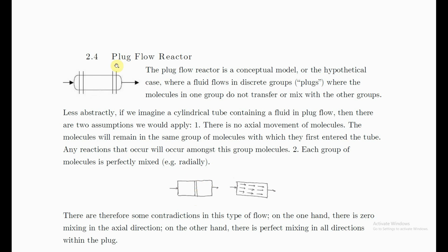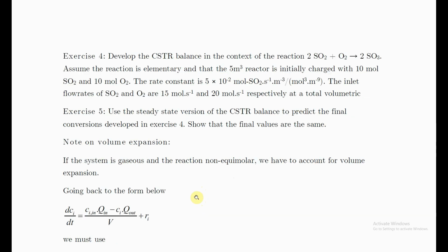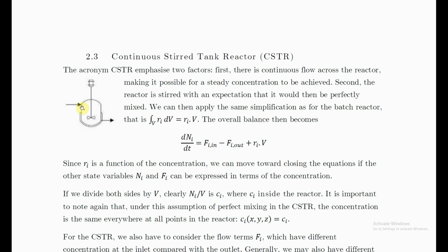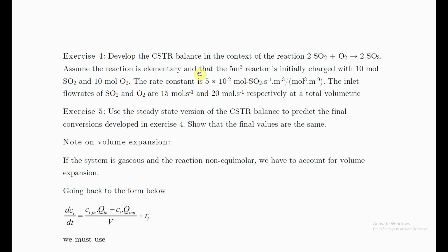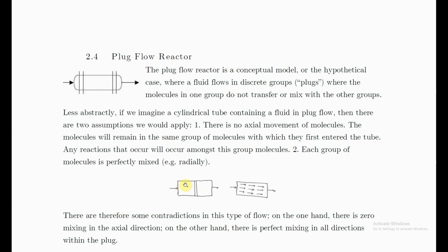So that's the name, a plug flow reactor. It flows in plugs, and each plug is its own entity, and it has all its behaviors internal to that plug. And if you like, that's the perfectly not mixed case. So we had the perfectly mixed case here. Every molecule was mixed identically across that whole reaction space, so you had one concentration everywhere. In this case, it's perfectly not mixed. Every molecule is held in its own individual space. It's chugging along with its peer molecules, if you want, and they're all coming in at the same time. They'll all spend the same time here, and they'll all exit at the same time. So that's the case of the plug flow reactor.